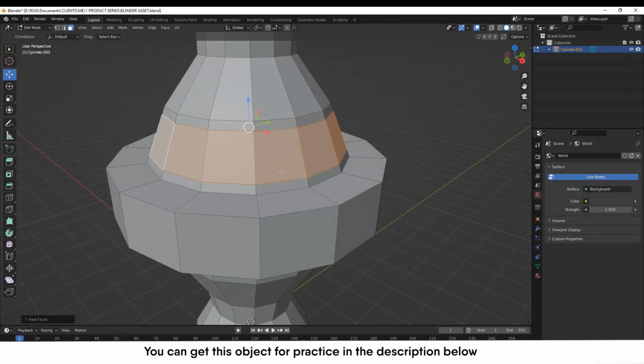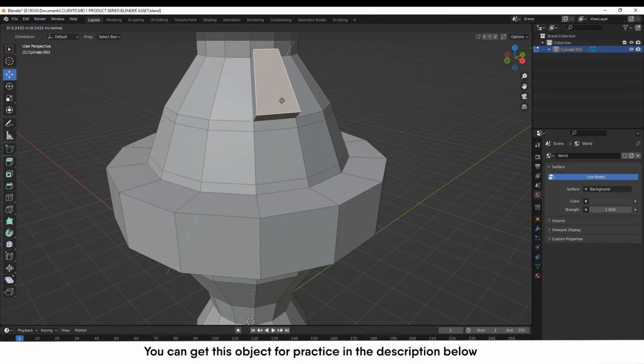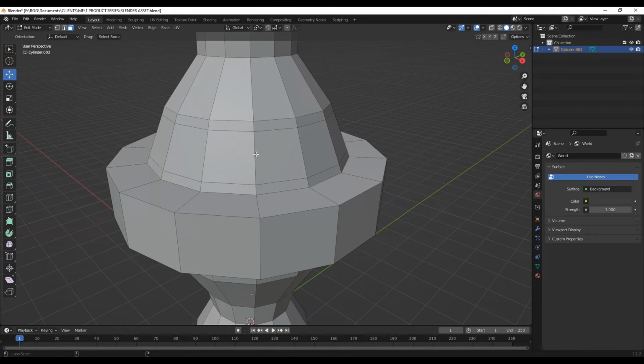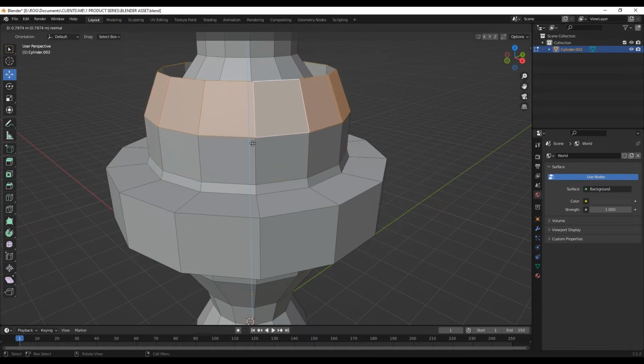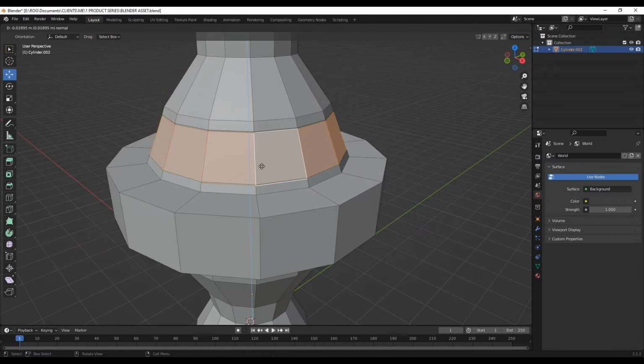So if I wanted to perform an extrusion on this face, first of all, let's see how the extrusion tool works. Let's select a single face here. If I hit E on my keyboard and I just drag outwards or inwards, you see that that's been extruded. But if I want to walk along these faces, so let's just make the loop selection again, Shift Alt and select this loop. If I hit E, it won't help me extrude this how I want to extrude it, because I want this to grow. I want this to scale together outwards.